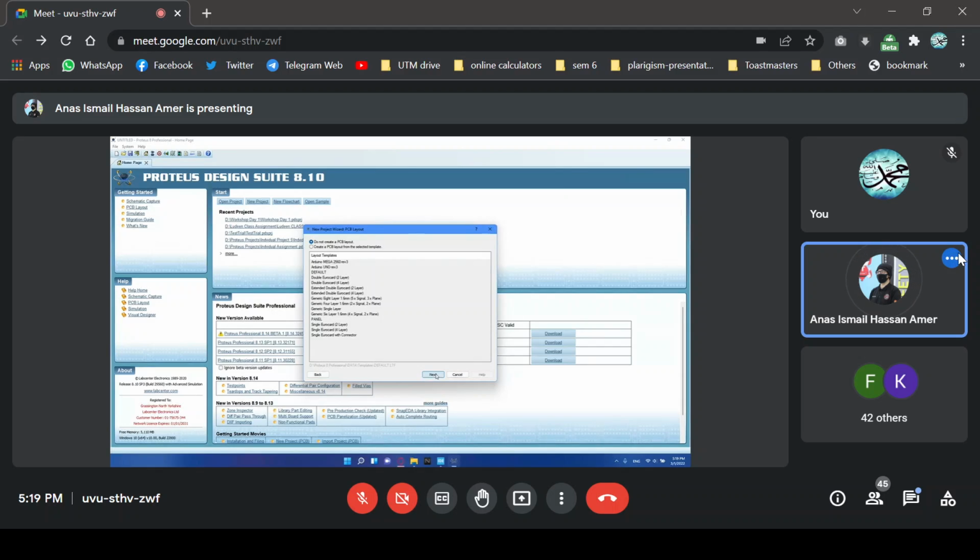And next, we'll choose create a firmware project. So the second one. For the family, we're going to use the Cortex M3. So just choose Cortex M3. And then for the controller, scroll down to STM32F103C6. I've already posted the name inside the chat.